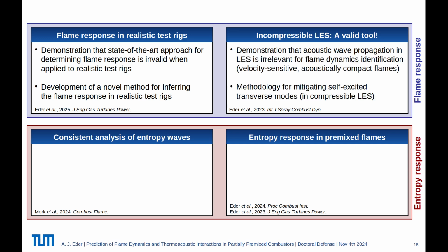We demonstrated that acoustic wave propagation in the LES is not relevant for flame dynamics identification, at least when we investigate velocity-sensitive acoustically compact flames. And we also developed a methodology for mitigating self-excited transverse modes, a common problem in compressible LES.